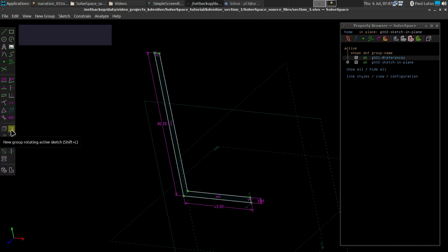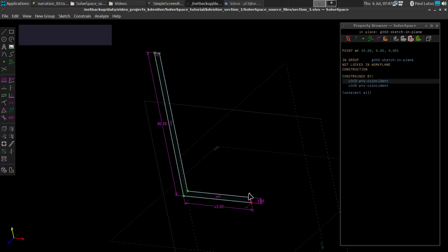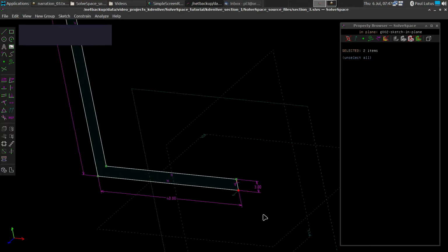so-called rotation. By the way, these two names are confusing. One of them's called a rotation, and the other one's called a revolve. And those are basically synonyms, but they actually do have different meanings in this program. You just have to remember how they differ by their position on the toolbar. So here goes, we're going to do this one. And what this one does is it always rotates through 360 degrees. But in order to use it, I have to specify an axis for the rotation, which I'm doing right now. Now we've established an axis right there.